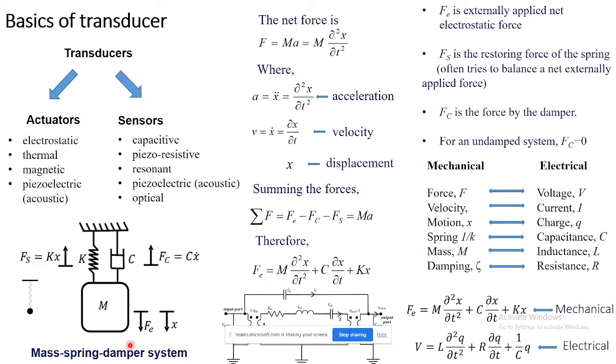When you design or fabricate a new sensor, how do you look at this characteristic of non-linearity as part of the design? Right. When we measure the characteristics of a sensor, let's say we designed and fabricated one prototype, we bring it to our lab and make a test bench, and we record our output readings with respect to our input quantity.